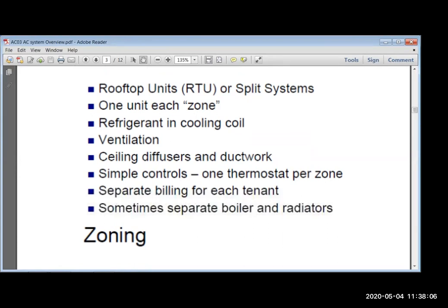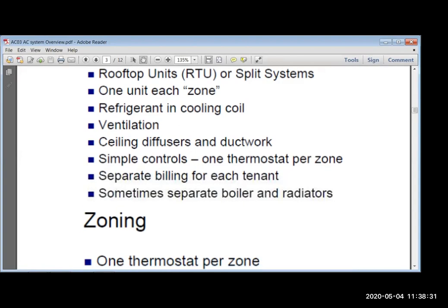Now, ventilation system. Ventilation means outdoor air, fresh air with fresh oxygen. Indoor dirty, polluted air must be exhausted from the occupied space, and an equal amount of fresh outdoor air must be introduced. But before introducing that outdoor fresh air, its temperature and humidity must be controlled. It must be cooled or heated, humidified or dehumidified, before sending to the air conditioned zone.